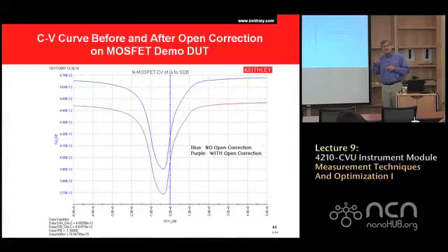And we did this with no corrections turned on. I don't know if I got my test settings in here. I didn't put the test settings in. This is probably done at a megahertz. So it's at about 4.5 picofarads, 4.65 picofarads, and here's our curve, all right?